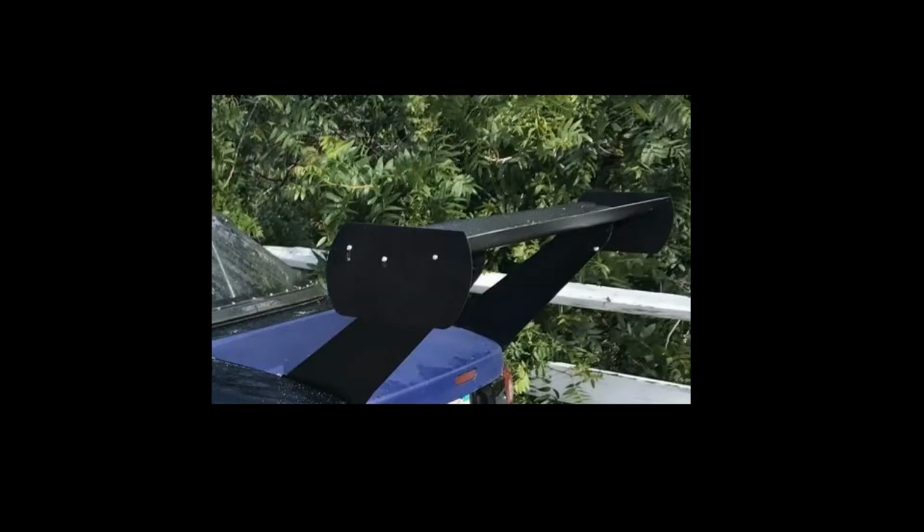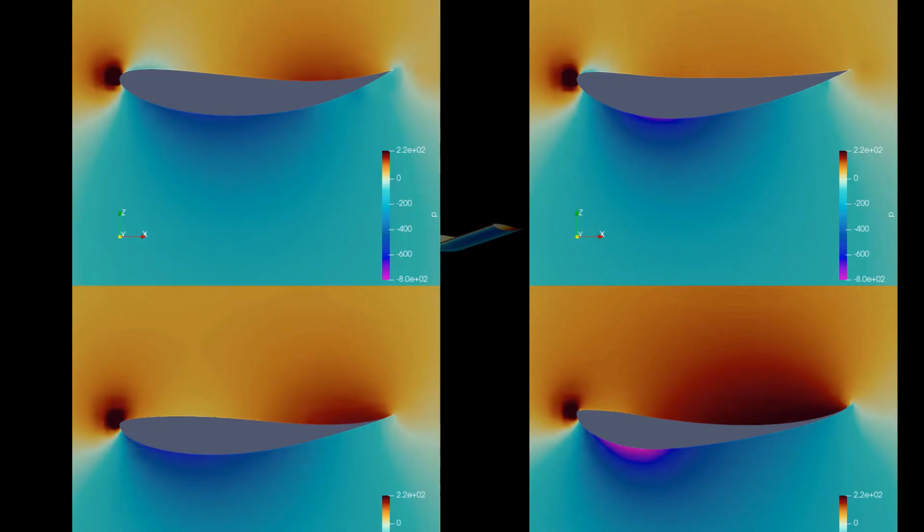Just choosing a high lift profile is a good start and good enough for amateur racing series. The next step would be to implement a direct design process that would take a series of profiles and analyze them in software. There are two programs, among others, that someone could use for this level of design: OpenFOAM and Xfoil. OpenFOAM could run basic wing profiles, even with endplates, on a laptop, but you'll need a method to get the profile into the software.